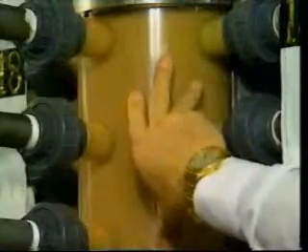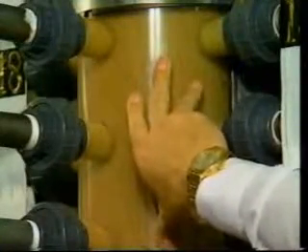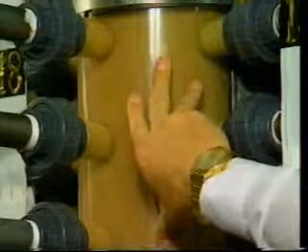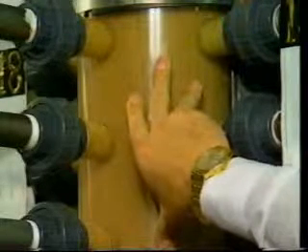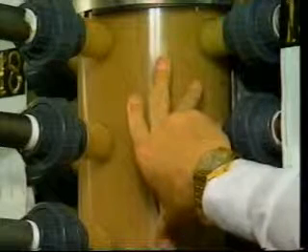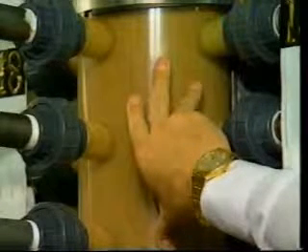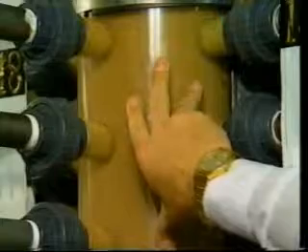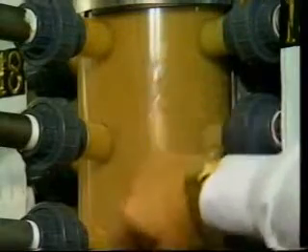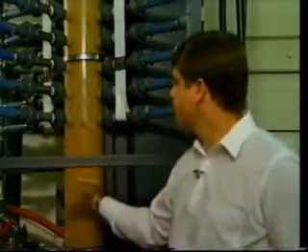With time, we've observed that the sand has settled out and has filled up the majority of the void, and in the field this would have normally been okay in such a short model because we would have had a sufficient reservoir and blank area above the top of the screen that was containing gravel. Had we had a much longer perforated interval, I'm not sure that we can count on having enough blank interval to allow for that much settling to occur and to fill the zone. So although the gravel pack was not performed in the ideal manner, in this particular case it would have been successful.